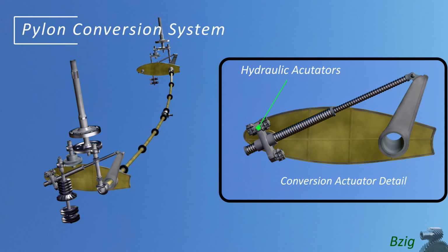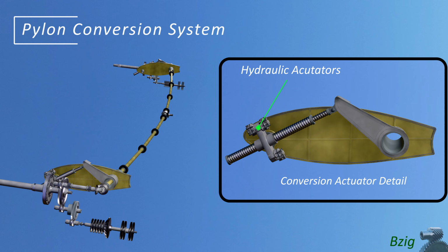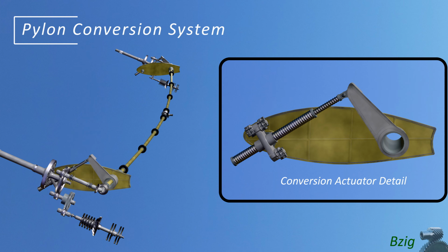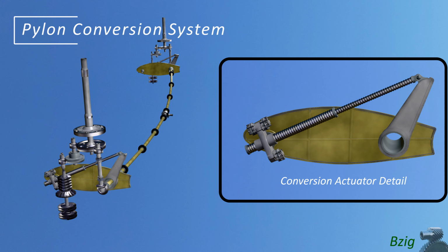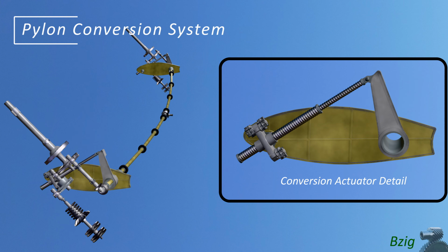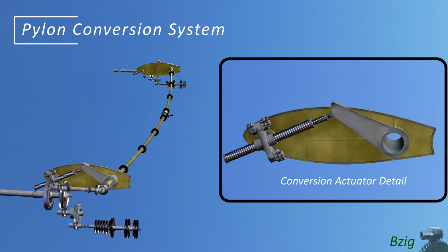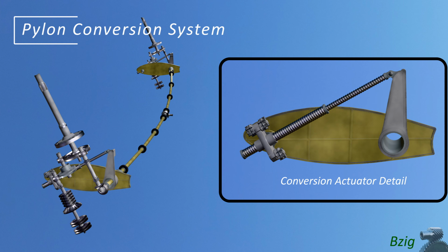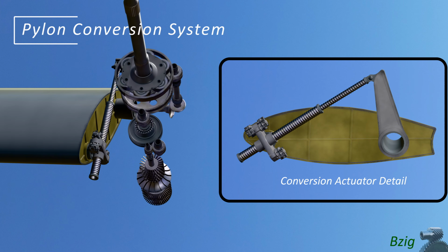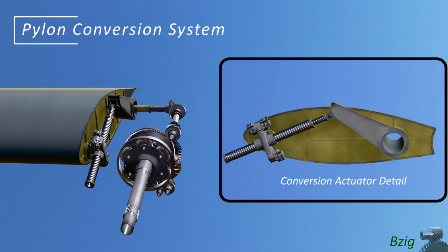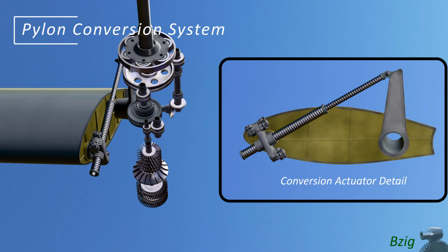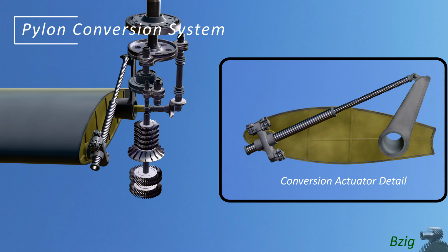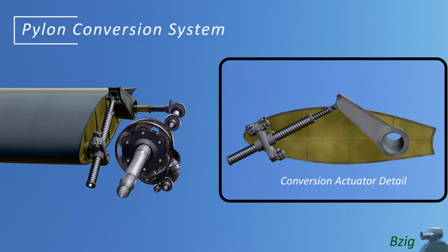I added 3 redundant hydraulic actuators to the animation, although different tilt rotors in history have used different means of actuation. Some have used electric actuators, and some achieve redundancy via a mechanical cross-shaft. There's no safety effect if the Pylon conversion system fails while in thrust-borne flight. The pilots would just land and give the aircraft back to maintenance.